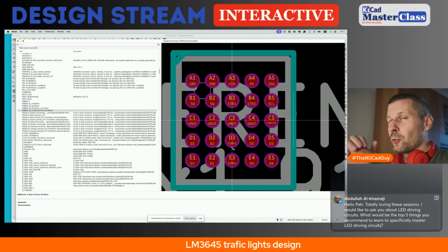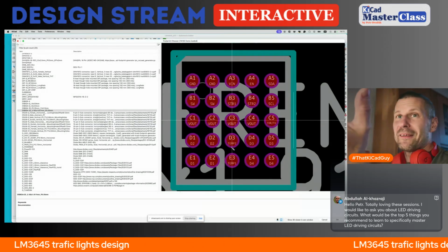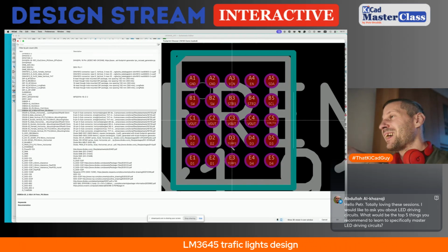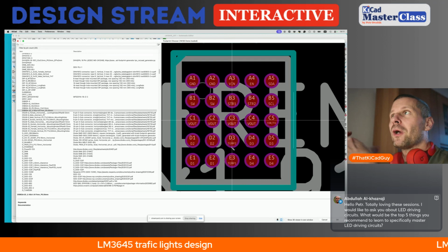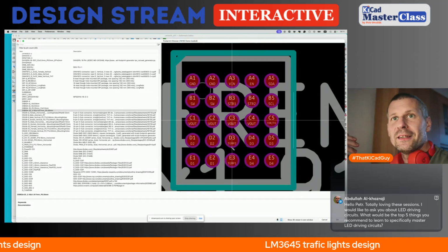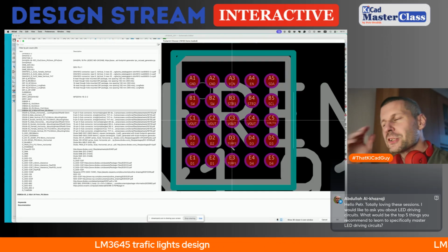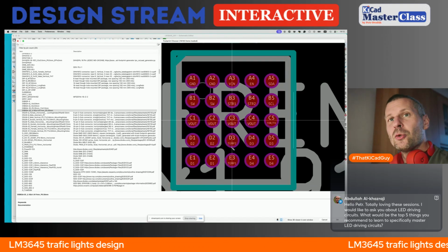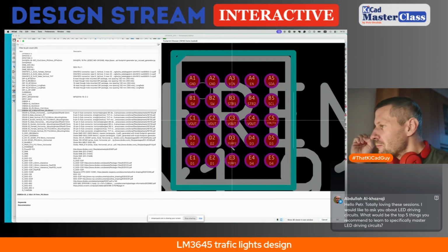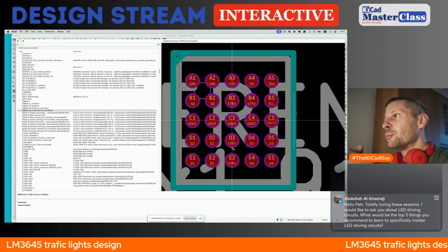So temp 2 should be configured at first, and the strobe 1, strobe 2, I think I will not use them. The boost driver is designed for, you can imagine, the controller of your cell phone LED flashlight on the bottom side of your cell phone, and the strobe inputs are dedicated to control the flash, the fast transient light effect of the boost driver.